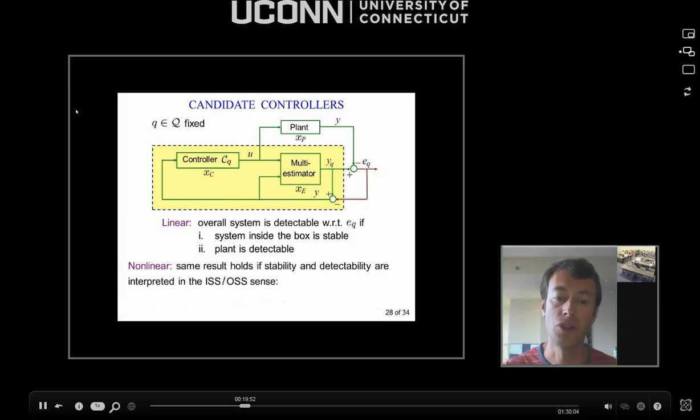They basically generalize the notions of both linear stability and also induced gain of the system. So you say that a nonlinear system is input to state stable, or ISS, with respect to some external signal V, if its response is upper bounded by a combination of two functions like this. The first one is decaying with time and increasing with the size of the initial condition.